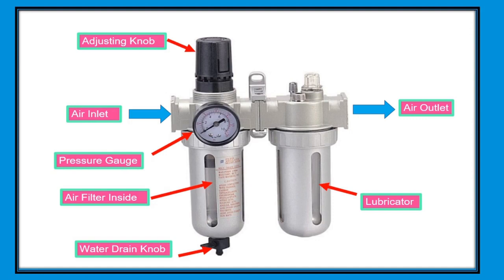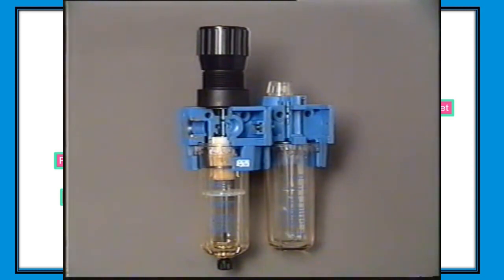If you want to adjust the pressure of the system, you need to pull this adjusting knob. Turning the knob clockwise will lower or decrease the pressure from the valve. Keep track of the number of turns so that you can go back to where you started.